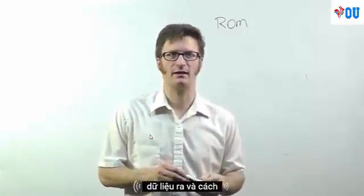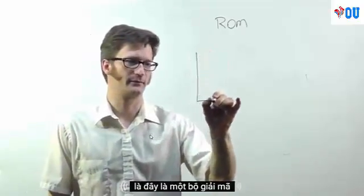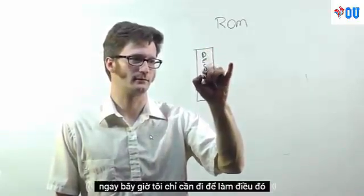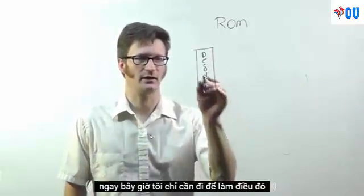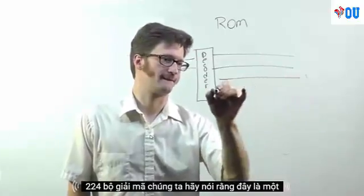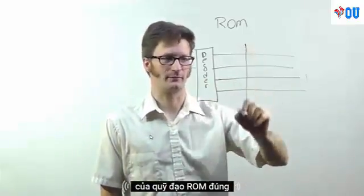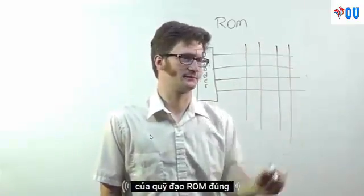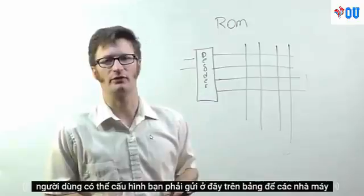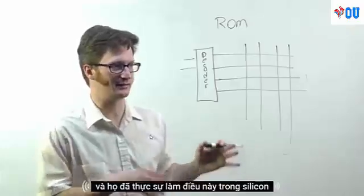And the way that a ROM works, and this is a very simplified version first, is here's a decoder. I'm just going to do a 2 to 4 decoder. And let's say that this is a 4-bit ROM. All right, so a ROM is not user configurable. You have to send a ROM table to the factory and have them actually make this in silicon.